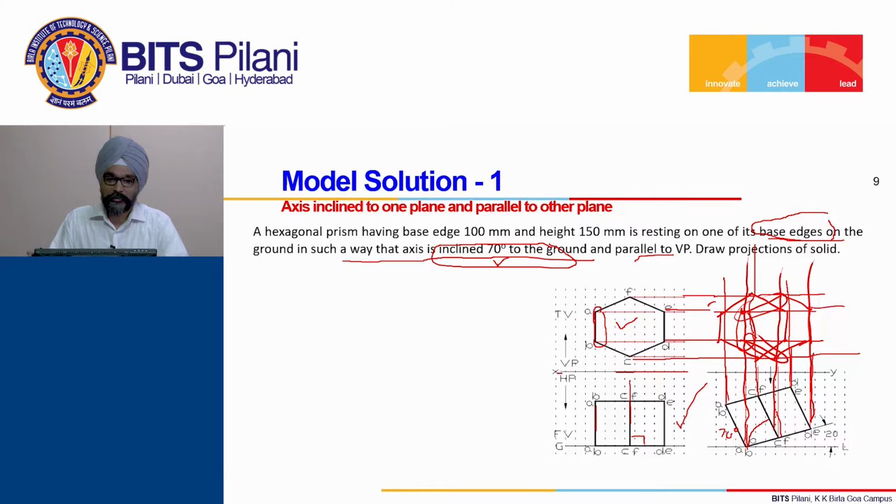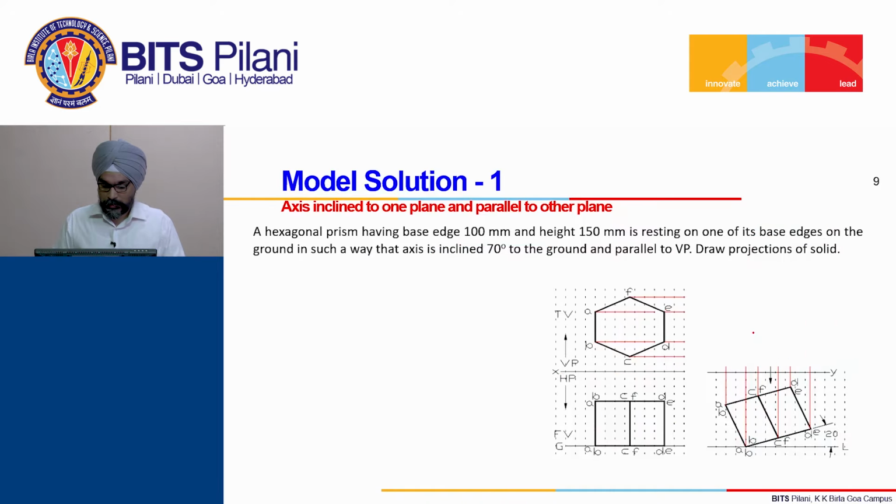For hidden lines we may use the cyan color, or the real practice in engineering graphics is to show them by dashed lines. In AutoCAD we are taking a convenient route. So, we change the line color to cyan if we are using the white background. If we are using the black background, we change the color to red. So, that is what we do to represent them. Now, I will show you the next position.